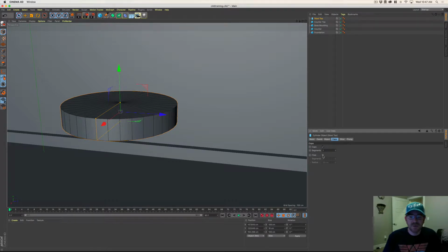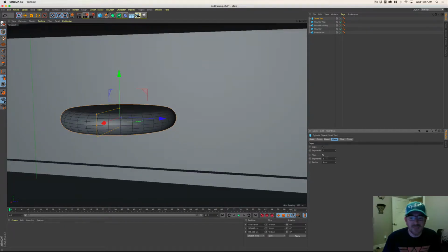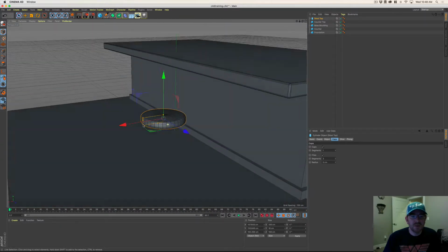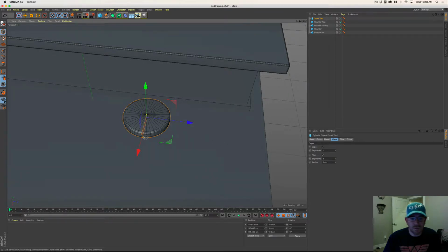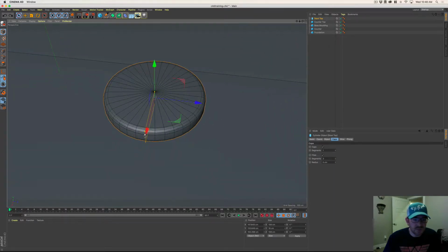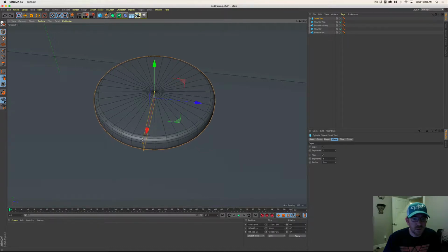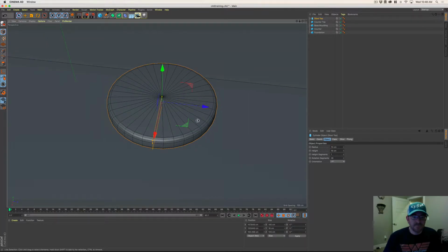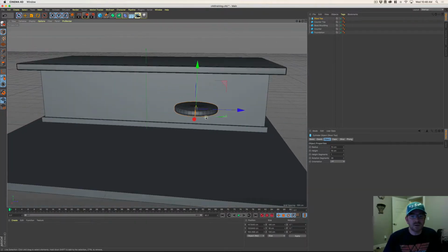This has caps. And that's the top and bottom part of this cylinder. So if I click fillet, it's the same thing. So I'm going to keep this consistent. I'm going to use a 3 and then a 5. Okay. Do that however you like. That looks like a stool top to me. We could pull, oops, don't want to do that. I want to pull this guy out a little wider. So maybe we make him 70. Looks like a stool top.